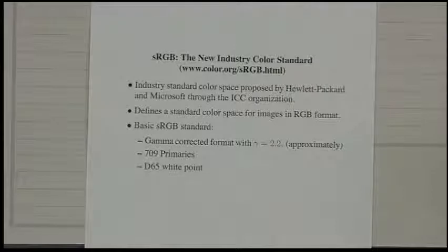That gamma approximates the linearity of the display, and the perceptual response of the human visual system. So if everybody now manufactures a display that's sRGB, you have a much better chance of having the same picture look the same on more than one monitor. You know it doesn't work perfectly, because if you look around this room, every single monitor is different, and we're all looking at the same picture. So even this doesn't work perfectly. But it's a lot closer than it was 10 years ago.